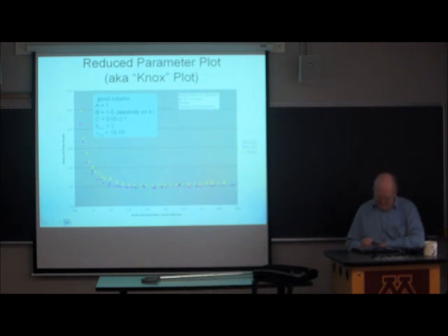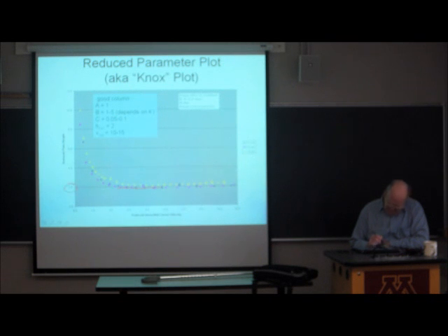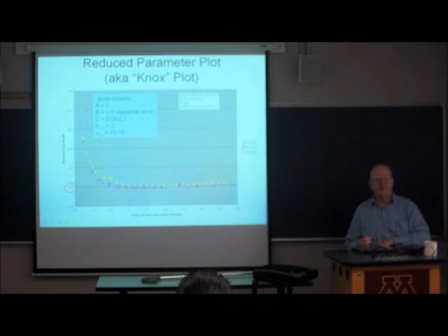And here's the magic. That's about the minimum reduced plate height for all three kinds of particles. And that's close enough to 2 to not need to remember 1.85. It's not going to make any difference.